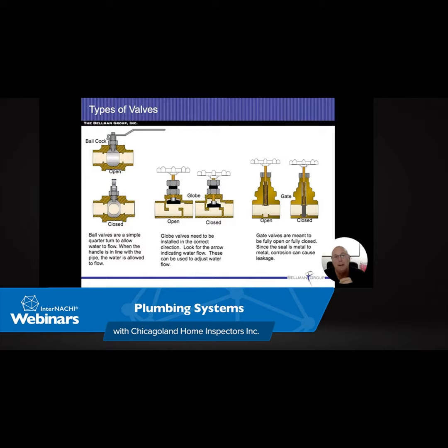But if it is in a zone such as California where they have their earthquakes, I want you to know that there's 2 straps that need to be on there. Those two straps should be 1/3 high and 1/3 low. They should be fastened to the structure. And the other thing, if you look at the bottom left, you're going to see that it's connected with a flexible appliance connector, just like we would do with a stove or a dryer. The purpose of that is that if this thing does fall off the wall and trip over, it's not going to break the gas pipe. It might have a slow leak to it, but it's not going to break the pipe and you get a big leak coming out of there.